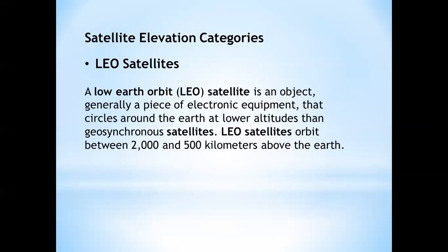Characteristics of LEO satellite: first is low orbit height. Next is that one revolution is completed in 1 to 1.5 hours. Next is low launching cost, low path loss, less transmission power, smaller antennas are to be used, less weight, small round trip delay, cover smaller area of the Earth, and short lifespan. Applications of the LEO satellites are scientific experiments, weather forecasting, mobile telephones, and remote sensing satellites.